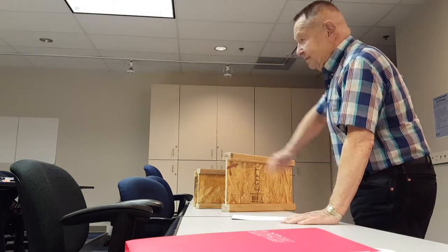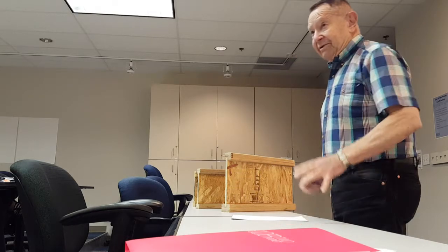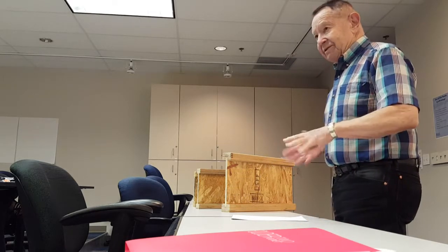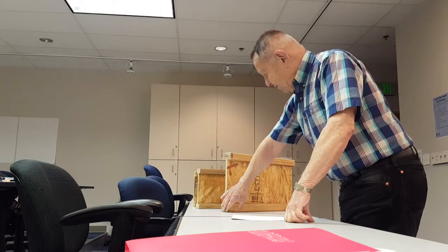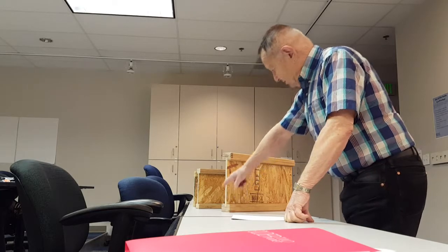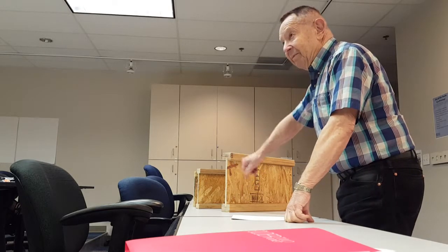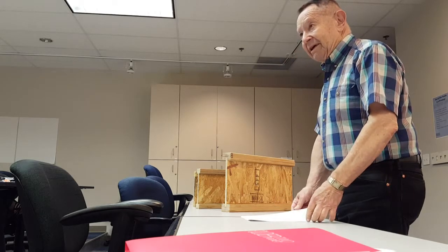So you can simplify your double integral when it's uniform material by just saying it's the area times the integral of the squared distance measured vertically. So that lets me work the thing as a single integral.